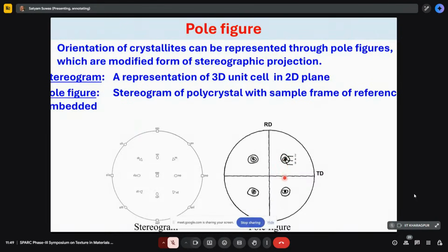These points represent, and now you can see how these are crystallographically located. Suppose this is a 100 projection, and these are the 4 points that we are seeing. So in the 100 projection, you will see that these 4 are located as 111. These are 4 111 planes, the way I am moving my pointer. So these are basically 111 reflections.